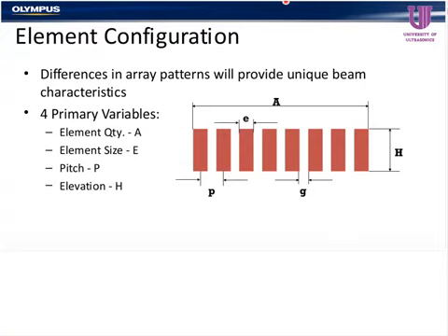In this particular slide, every transducer is built a little bit differently in regards to how the elements are patterned inside of the transducer. Now, this may not sound like too much of an issue, but depending on the spacing of the elements, how large the elements are, and how many of them you are using will affect the way the sound travels through the part.